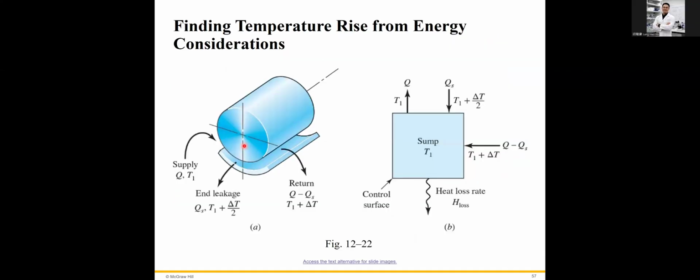I just quickly went through this figure. Q is the flow rate, meaning the lubricant is pumped into the clearance between the journal and the bushing, and it returns to the oil pan. It's the inlet and outlet, so it's a circulation from where you fill in the lubricant to where the oil returns.